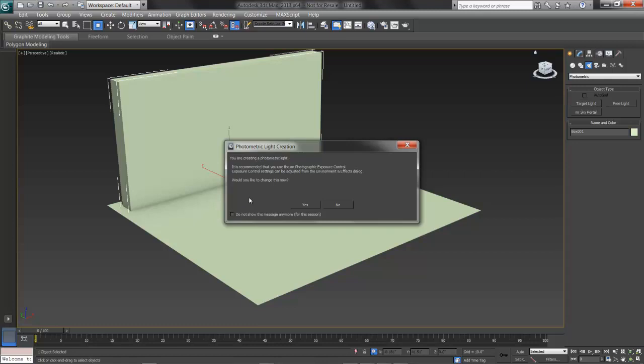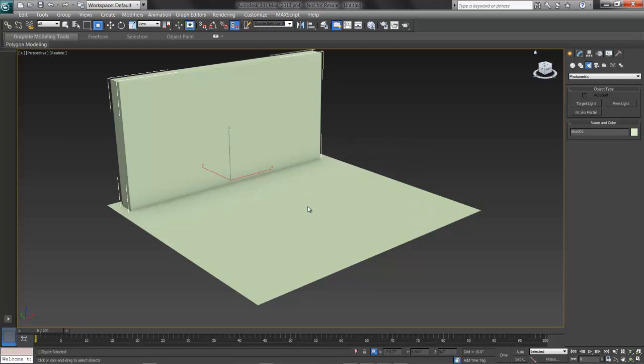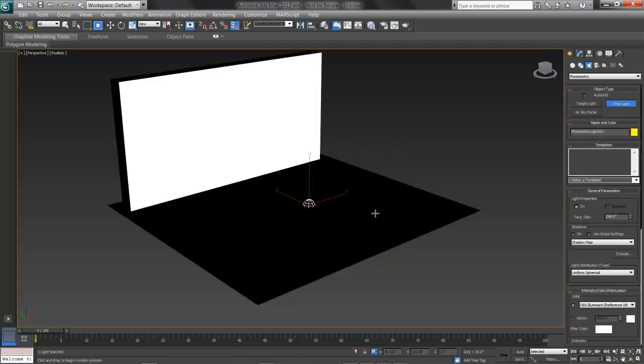And the reason we do this is that lights need to be seen by a camera to look correctly. And if they aren't seen by a camera, they are essentially way too bright to see. So we tone map them with a photographic exposure, allowing us to see the lights through a certain camera setting. I'll click Yes, and then I'll make a light in the scene. Instantly my scene goes dark on the bottom because my light is on the floor.